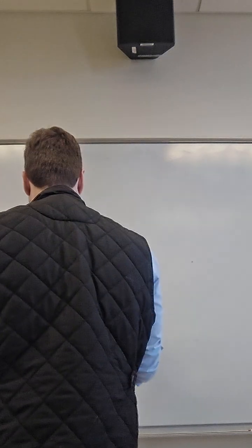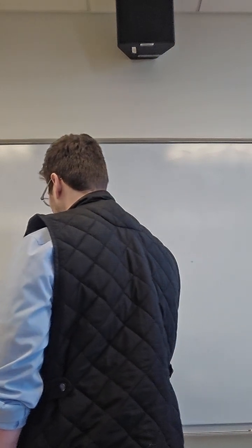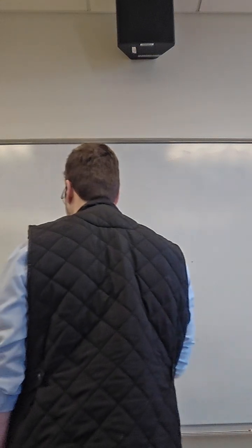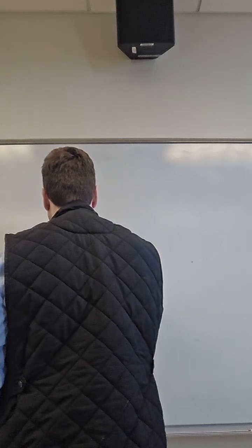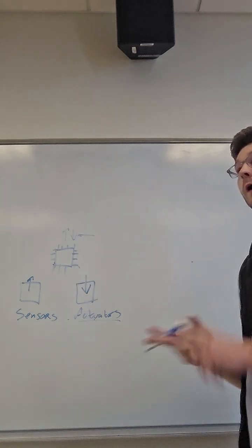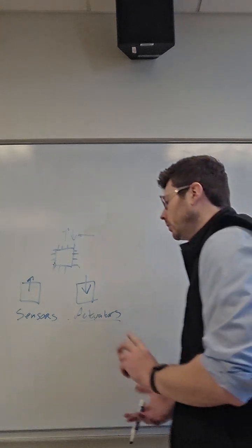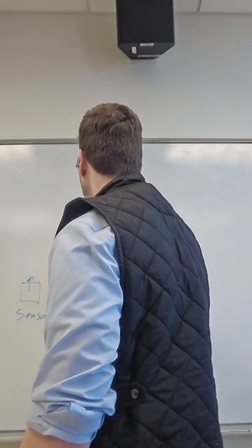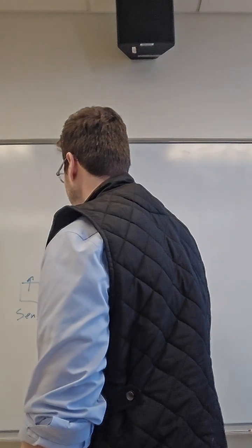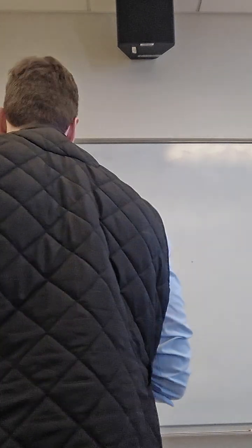Now we have to get this data either to this chip so it can fire the motor, or from this chip so it can report its information. So we're sending data up or we're getting data down. How we do this is another implication. Do we use a wire? Do we go wireless? If so, what protocol do we use? Do we use BLE? Do we use Wi-Fi? Do we use LoRa? Do we use Zigbee? What do we use? I2C, SPI, UART, all that jazz. That is getting the data out of our chip and starting to get it into the system.